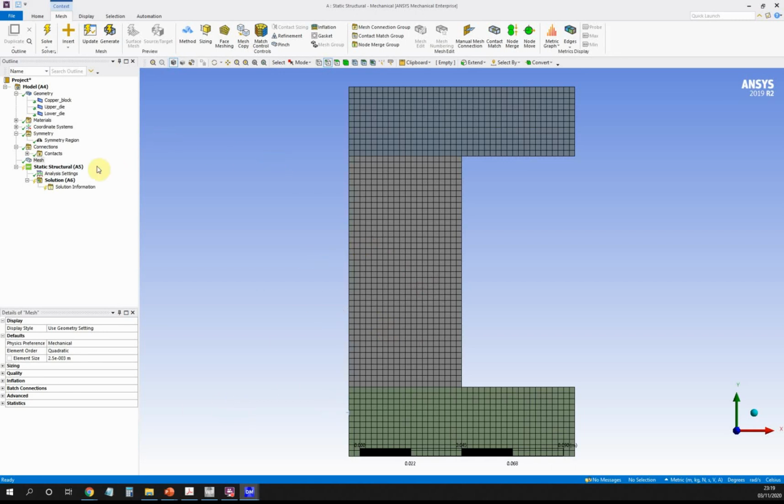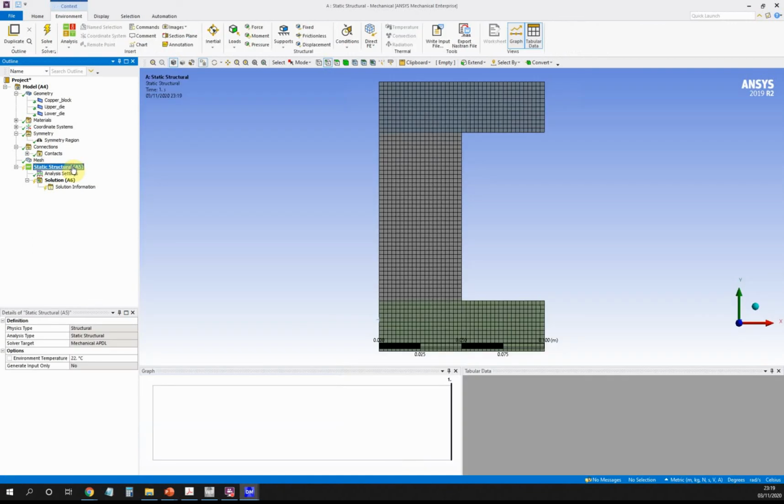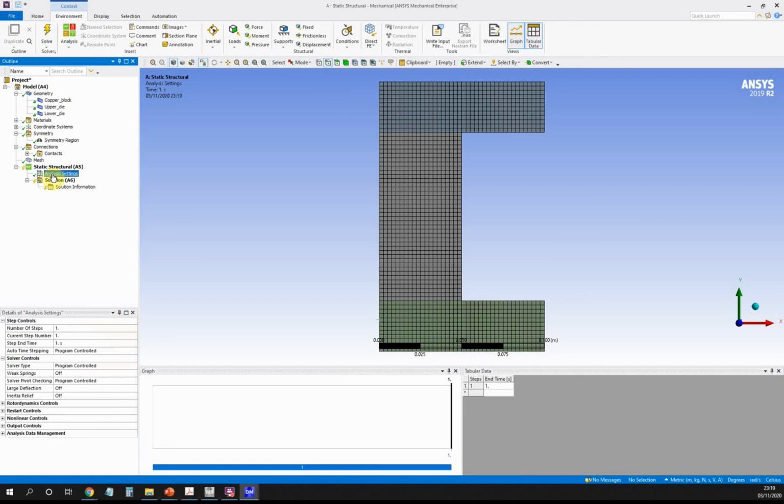Okay, so moving on down then, go to our static structural, and we have to change a couple of things in the analysis settings here. So if we click on analysis settings, the first thing we have to do is here we have this large deflection option. If you remember, a normal linear static analysis only works inside the elastic region, below the yield stress, where we're not getting very much deformation. The yield stress normally corresponds to a strain of 0.2%, which is very small. So here clearly we're going to be straining to 25%. So we have a 25% reduction in height.